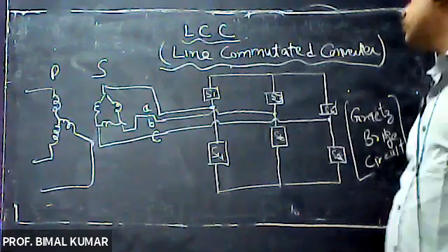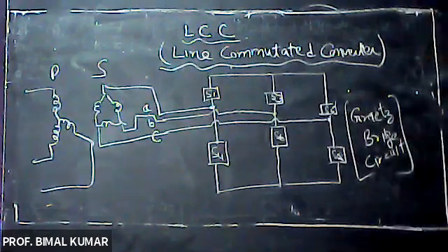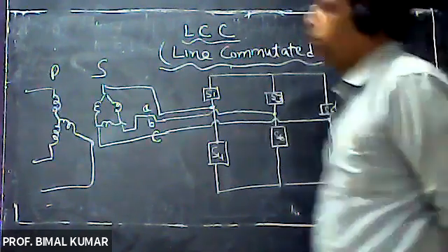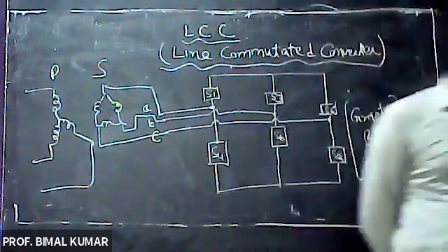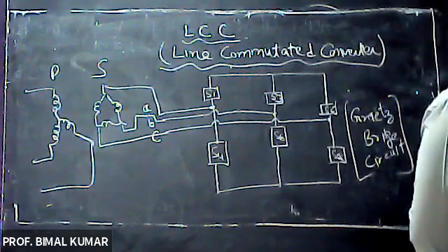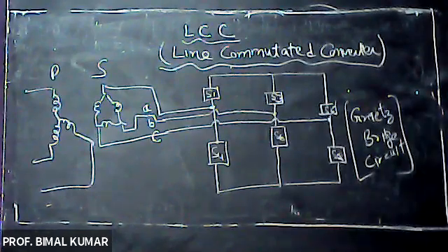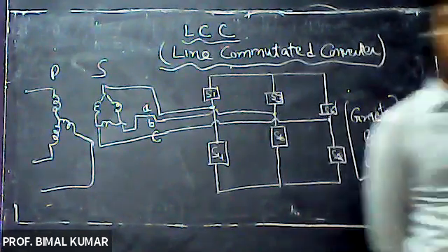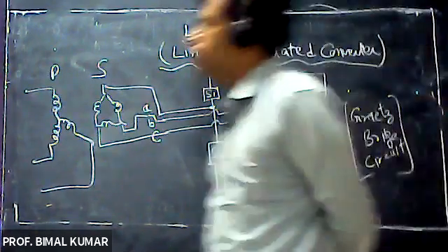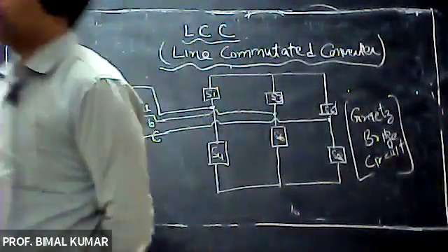That means purpose number 2 and purpose number 3 may be solved with an auto transformer, but galvanic separation cannot be provided in the case of an auto transformer.